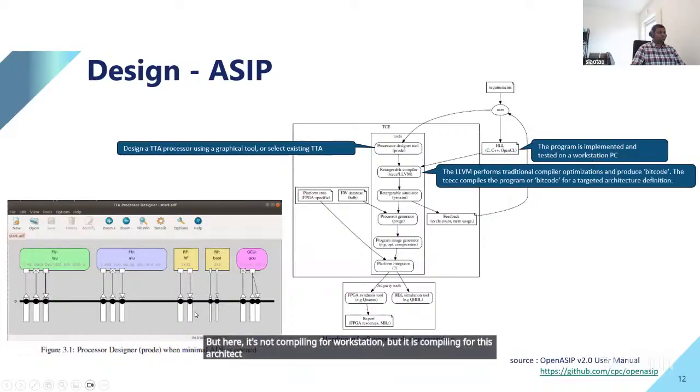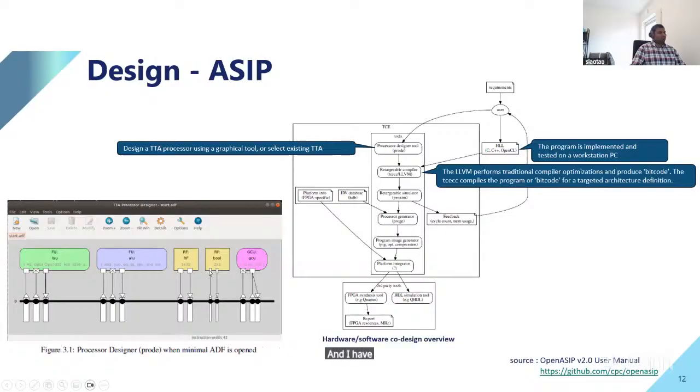And you are saying, okay, I have this ALU, and I have only these instructions in my ALU, and I have a global control unit, and I have these registers to work with, and I have a load store unit, which is connected to the memory. So basically this compiler knows what resources you have from a hardware point of view.